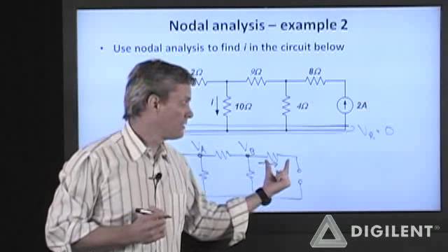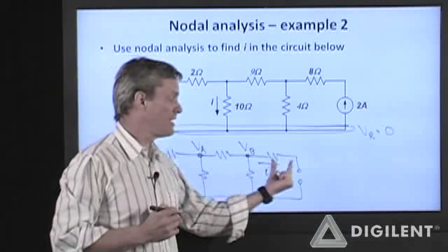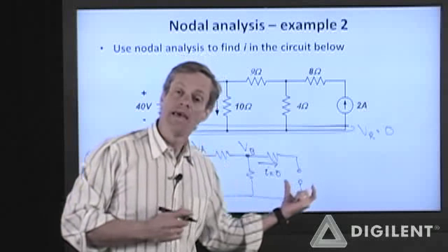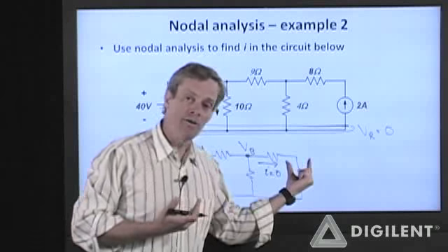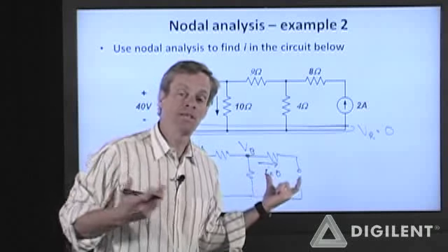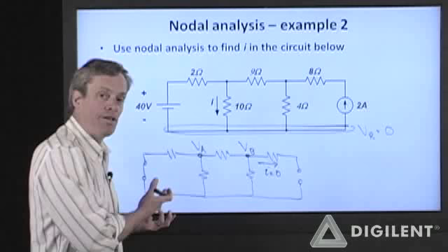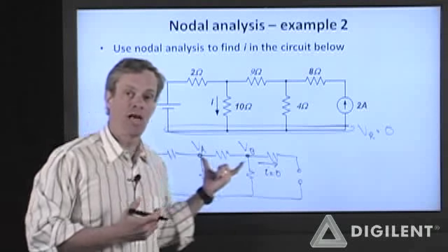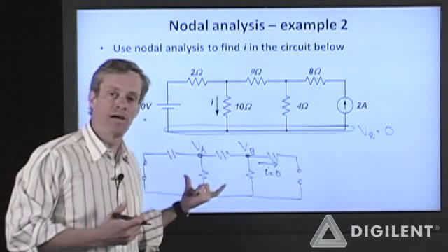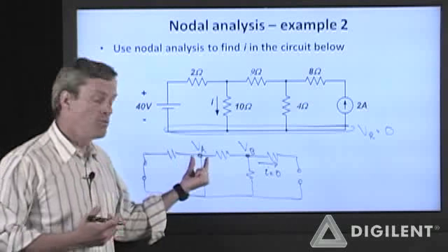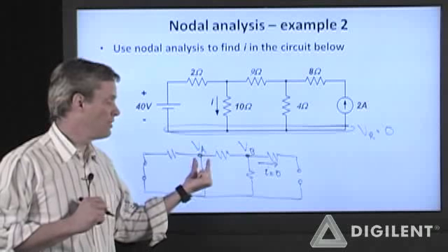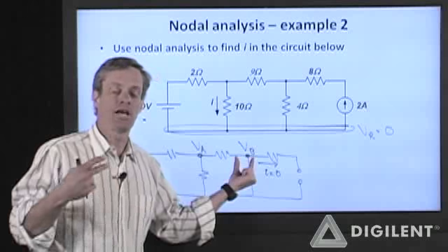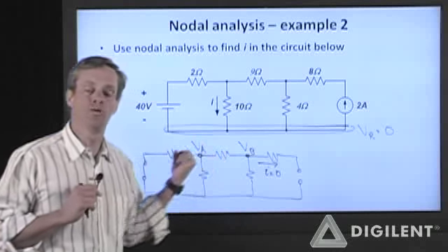Later on, we'll take a look and see what happens if you misidentify this and say that this is an independent voltage. If you keep your wits about you, nothing bad happens, because you remember that nodal analysis comes from KVL, KCL, and Ohm's law. As long as you're consistent about applying those, some of the details about nodal analysis don't matter. But at the moment, we're going to claim that the only independent nodes are here at V sub A and V sub B. I have two unknown voltages. I need to write two equations, which I'll do on the next slide.